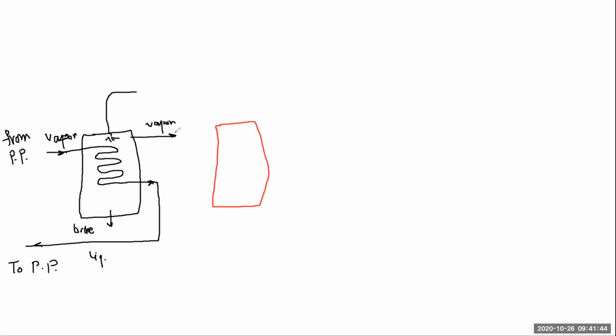another evaporator. This vapor is going to condense, let it condense inside the tubes here. So this is going to be part of the product that we have here, M dot from first evaporator. And the brine which is leaving here is going to be taken. It's still hot. So we can take this quantity and we spray it here. So we are making use of it again.